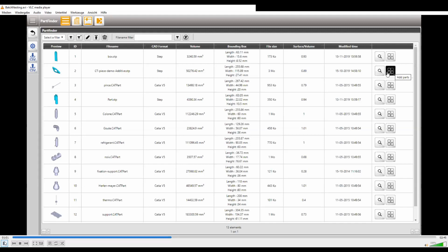And then based on these parts you want to print, set up your shop floor, your machine park, and then send, like in a web shop, just add the parts to the shopping cart, in the different print jobs, and the parts are then automatically 3D nested with the criteria you can set up for each part individually. And yeah, you get a seamless workflow to fill up your machines.